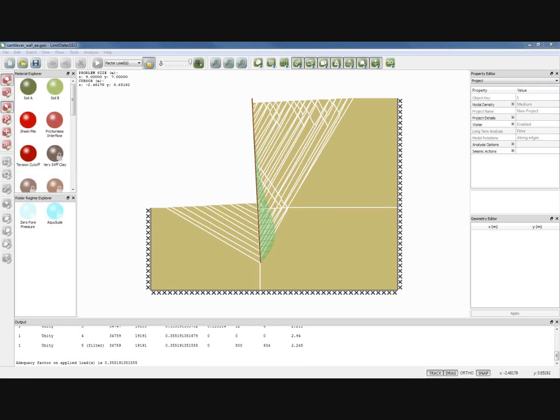I've got a question about modeling of friction. So in plastic analysis, friction is modeled as dilation. That means that, if you're familiar with plastic analysis, the normality is imposed in the analysis. The analysis is a rigorous plastic analysis. Generally, when you have friction modeled as dilation, if you have very confined problems, that can cause a problem. So if the soil is very, very confined, the dilation can cause kind of locking.